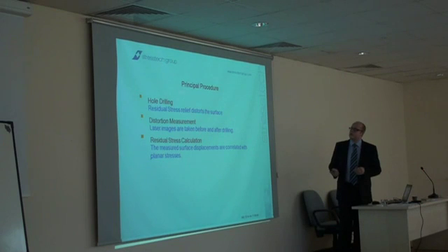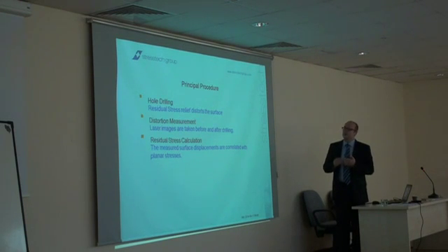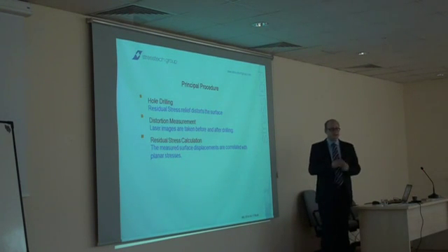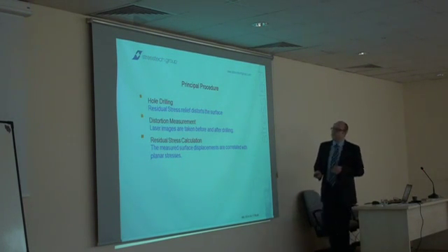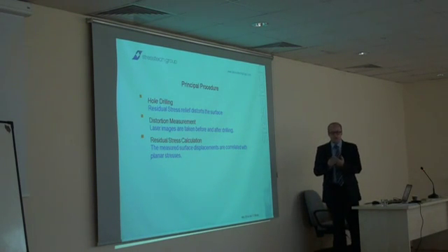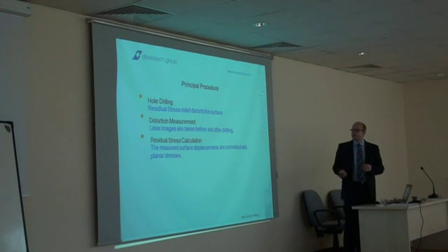So with hole drilling we have to drill a hole, and we have to relieve residual stresses in the sample surface, which means that we have to take laser images before and after drilling so that we can compare the two sets of images. So what we do, the measured surface displacements are correlated with planar stresses.